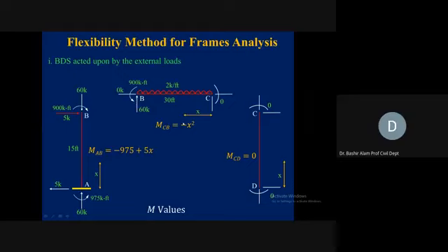Now joint D has to be in equilibrium. So 0 load is transferred here internally, but this 5 kip is externally applied. Why are we not bringing this to the horizontal member? Because if we bring it to this horizontal member, then it has to be supported by C. From C it will come to the vertical member, but then there is nothing at D to support it. So this 5 cannot travel towards the right by adopting the BCD path. It has to adopt the BA path.